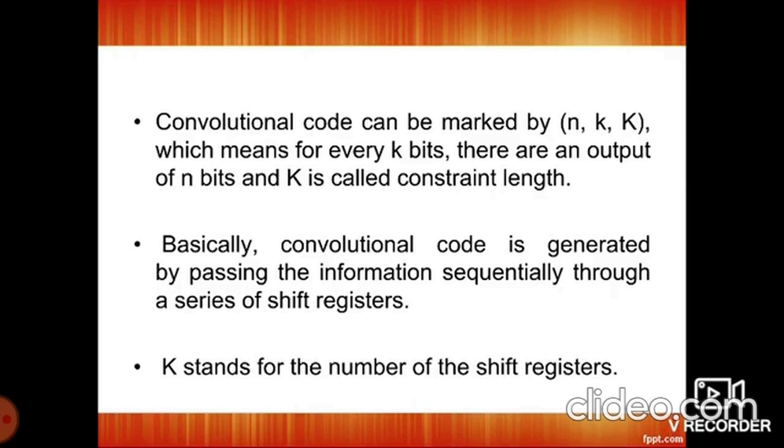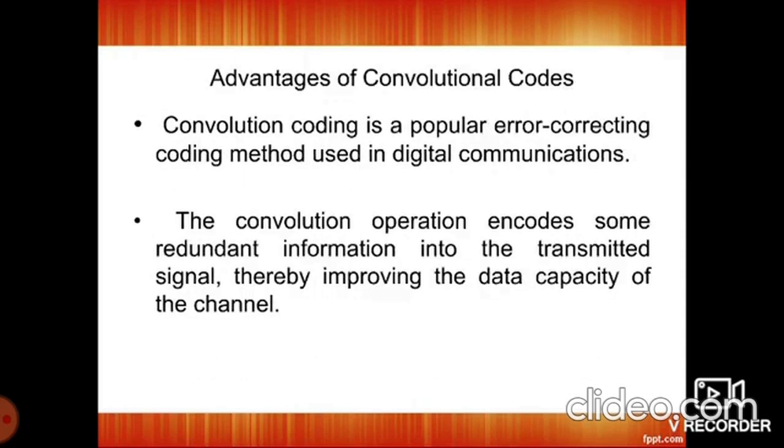Whenever a message bit is shifted to position m, the new values of x1 and x2 are generated depending upon m1, m2. The convolutional encoder consists of one shift register having the incoming bit represented by m, and the flip flop stages represented as m1 and m2, and it uses modulo 2 adders. x1 and x2 are the two modulo 2 adders, with inputs from the flip flops.